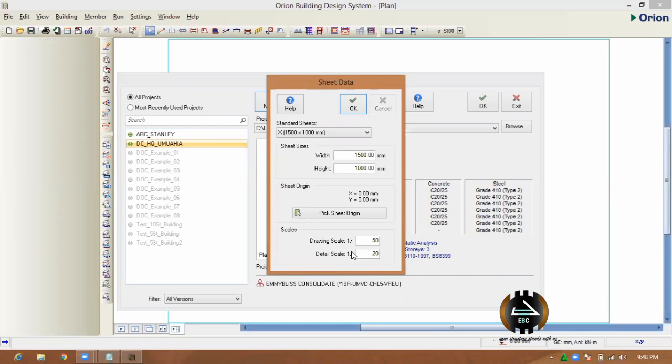So now, for you to understand that, if you want your drawing to be bigger and your details to be bigger, you can actually increase this from scale 20. You can take it up. So you know the rule now. The higher the scale, the smaller the drawing. So if I have a drawing at scale 100 and a drawing at scale 75, 1:75 is not the same thing.